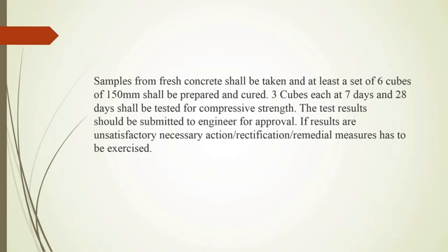The samples for fresh concrete shall be at least 6 cubes. Each set of 3 cubes shall be tested at 7 days, 14 days and 28 days for compressive strength, because concrete cubes are tested for compressive strength. After that, the results are submitted for the engineer's approval. If the results are unsatisfactory, rectification and remedial measures have to be carried out.